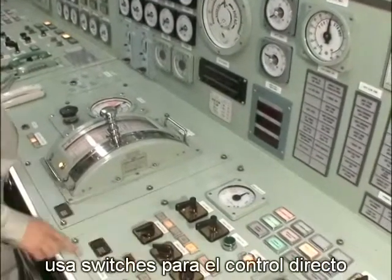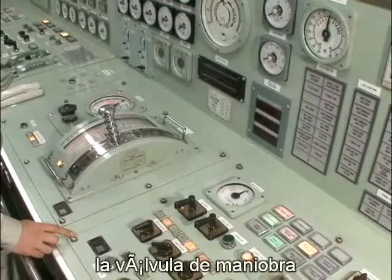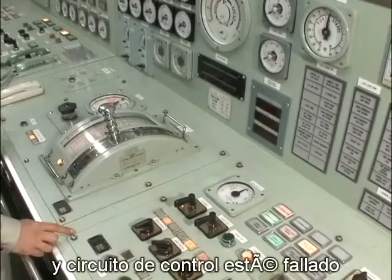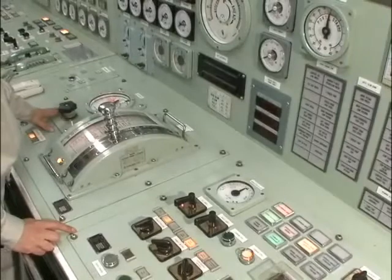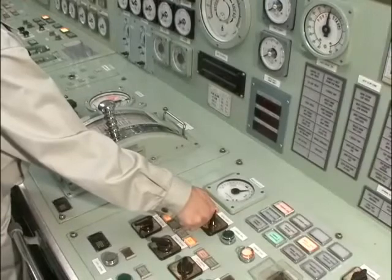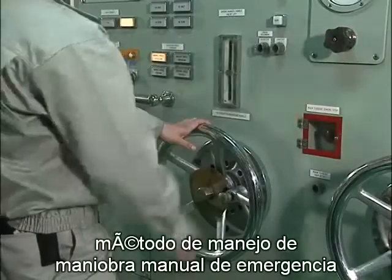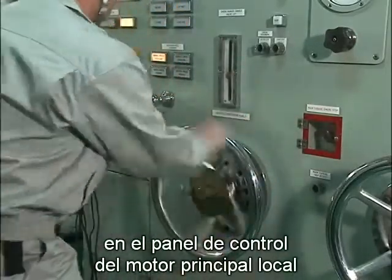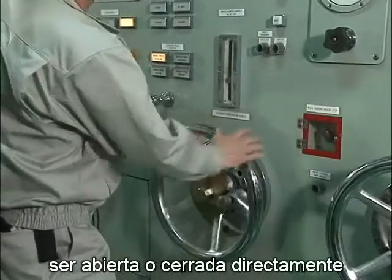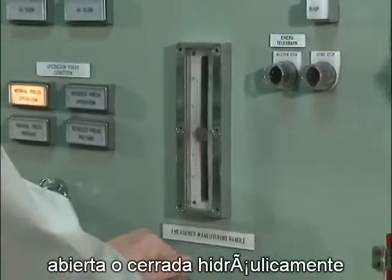Direct switch control mode uses switches for direct control on the control room console to directly open, close the maneuvering valve electrically and hydraulically in the event the lever control mode control circuit has failed. Another is the emergency manual maneuvering handle method at the local main engine control stand. This method allows the maneuvering valve to be directly opened or closed by a manual handle to operate a linkage when the valve cannot be opened or closed hydraulically.